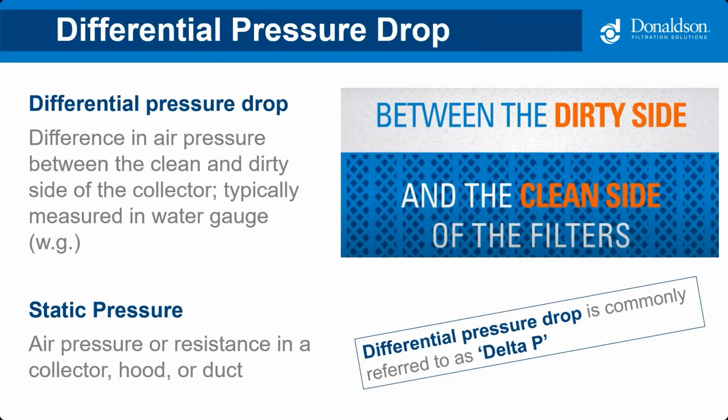The difference in that pressure is called the differential pressure, and it's typically measured in water gauge, or inches of water. The reason this is so important is that I always call it the stethoscope, the doctor's stethoscope, right? He grabs it, throws it on your chest, a couple deep breaths, you get lightheaded, etc. But it really helps to tell real simply what's going on inside the dust collector. So that's going to be one of the very first things I always ask: what's your differential pressure drop? Because it's just that important.